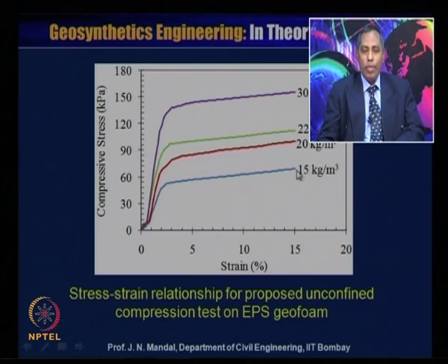So, from this figure we observe that the compressive stress value is increasing with increasing density of the expanded polystyrene geofoam. Even then, at a particular minimum strain value, the compressive stress value lies almost on the same line. So, this compressive stress is very important to us.